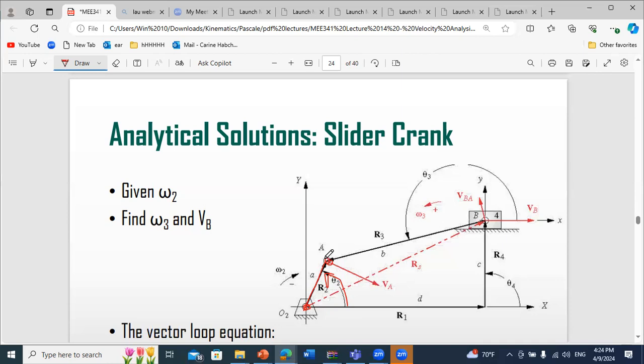For the coupler, also, you are joining two pivots, A and B. So also, B is of constant magnitude, but this angle is varying because if you have a new position of your block, automatically this link will change in angle, and this one also will change in angle. You have a new angular position, okay?